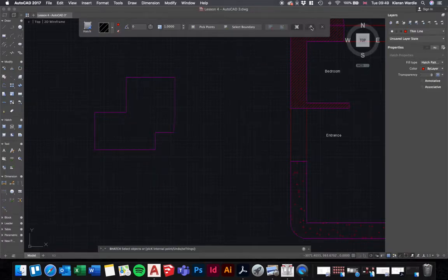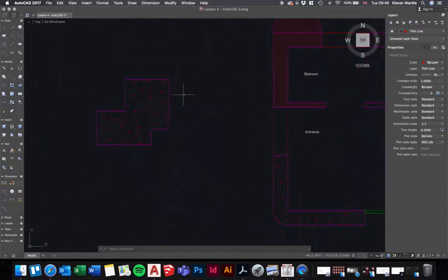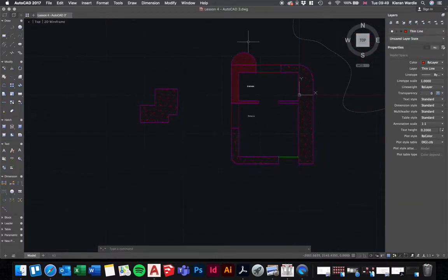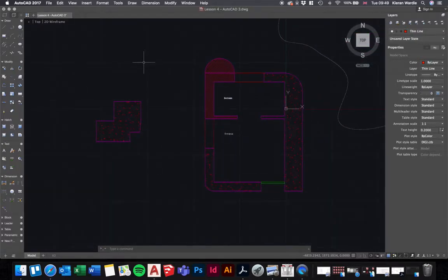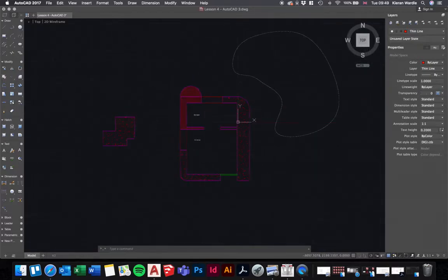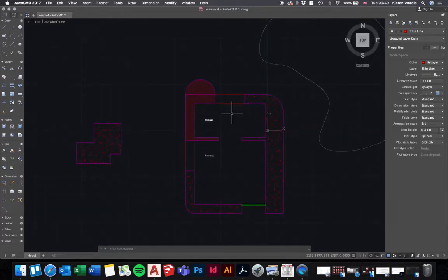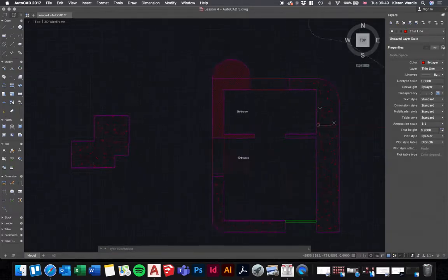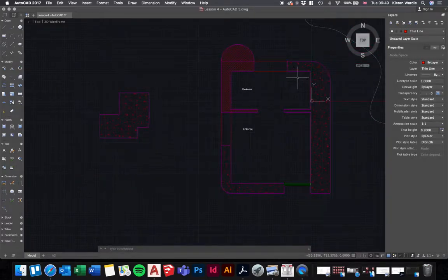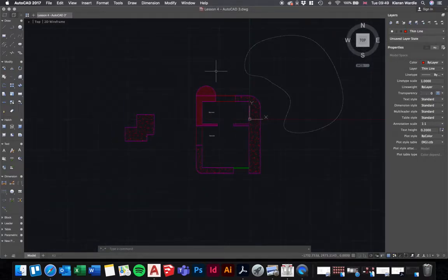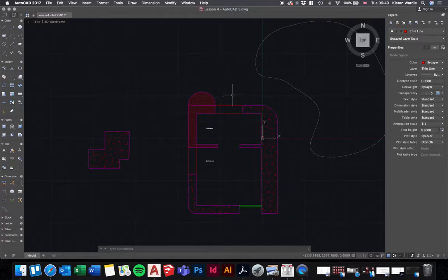And now I can select this hatch and fill it. So you can start to select the layer and then draw instead of doing it the other way around. Now, we've used this to define lots of different lines. It's worth noting, I said before that we want all of these to print black. This one's going to print grey, but they're all going to print black and white.